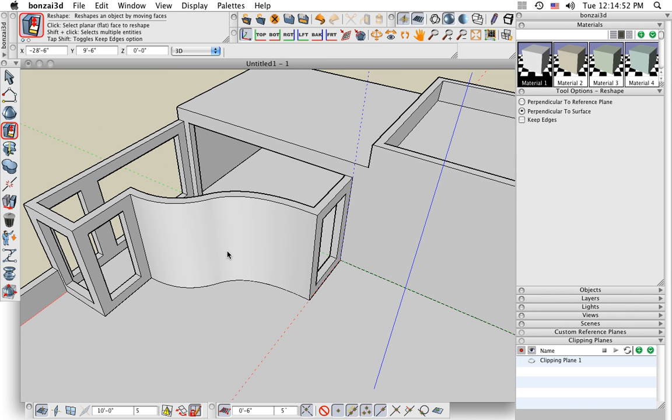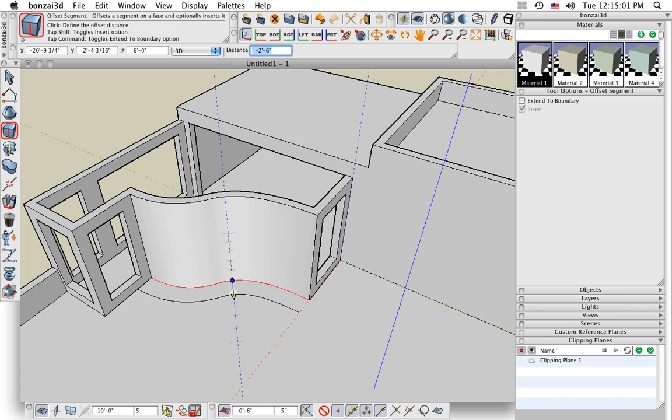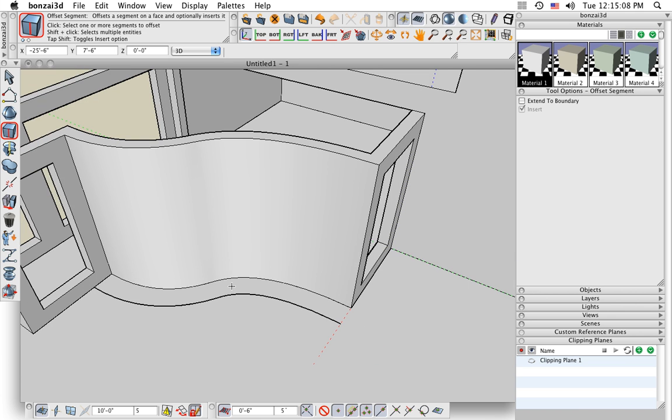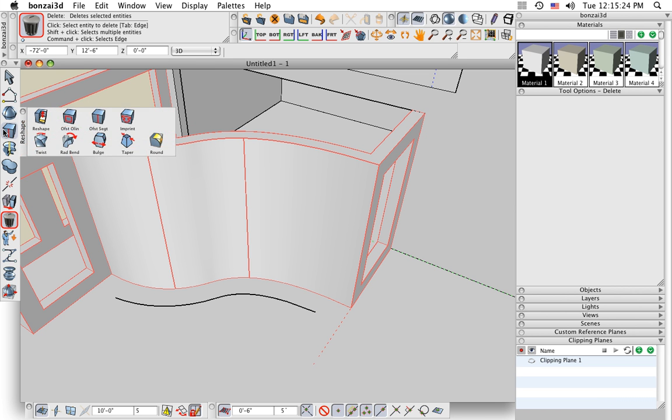We zoom in, and I'll start by offsetting again. Offsetting really is a great tool because you can just use existing geometry and keep working with it. So I'm just creating a parallel copy of that one bottom edge here. And I'll use the line break tool to clip off the end. So I just break this apart right here and right there. And I will delete the small pieces that I have clipped off. You will see in a second why we did this.